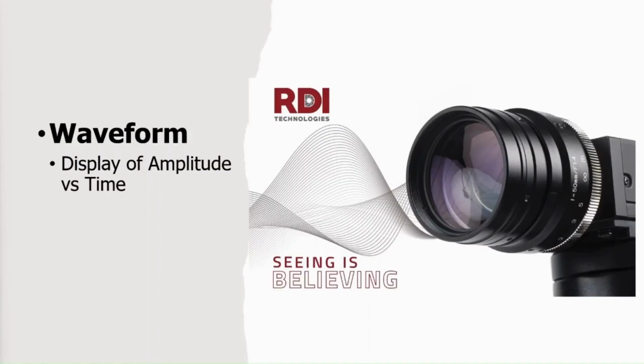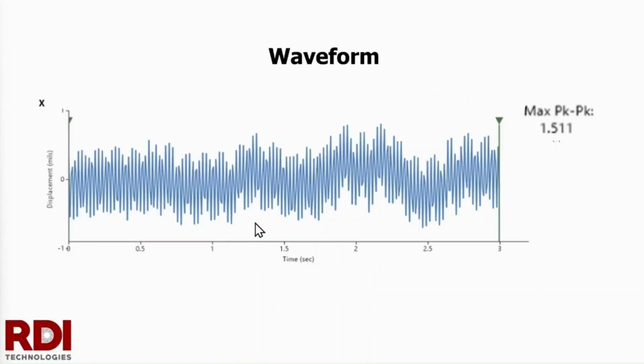Another type of vibration plot is known as the waveform. And the waveform is a display of amplitude versus time. So this is a sample waveform where we still have an amplitude scale on the left-hand side, but the amplitude scale doesn't start at 0 and just run up. We've got 0 in the middle, and we've got the positive and negative values in this waveform representing motion in both directions from the resting position. And then instead of frequency on the bottom, we have time.